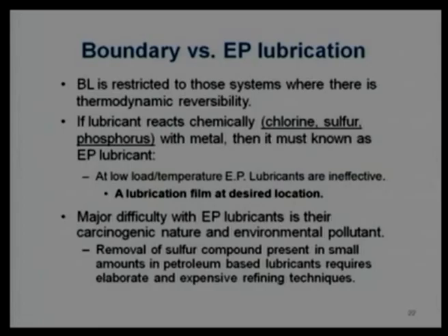So, this kind of additive gives optimum performance as per the requirement. Wherever it is required, it gives. It does not make lubricant film everywhere. If the gear pair is coming in contact, wherever the contact point comes, lubricant film is made at that point, because of the high temperature, high pressure, and corrosion occurs for some fraction of a second there itself.